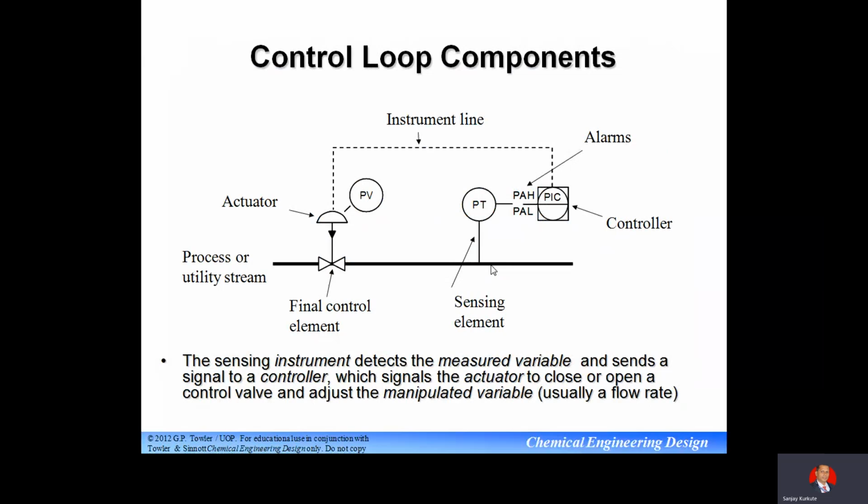Let us come to the feedback control system now. See the set point, controller, manipulated variable, measured variable, and how the system works. The controller computes the error between input and set point. There will be a comparison between input and set point, and it adjusts the output based on the control algorithm. So the complete controller system has this type of operation. Then typical algorithms are P meaning proportional, I meaning integral, D meaning derivative. So we may have P, PI, PD or PID type of control algorithm.